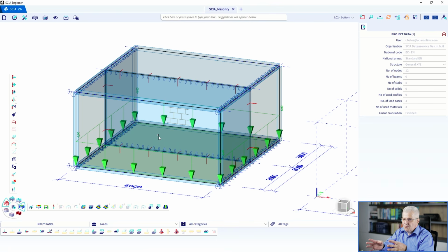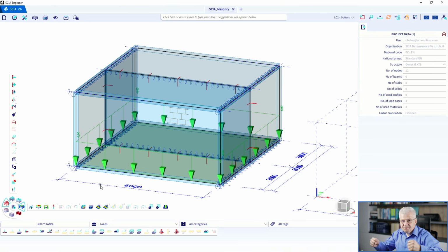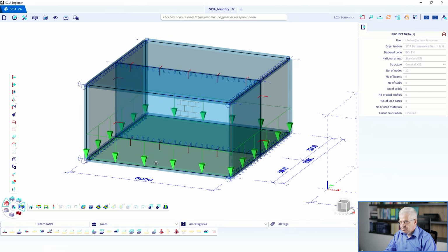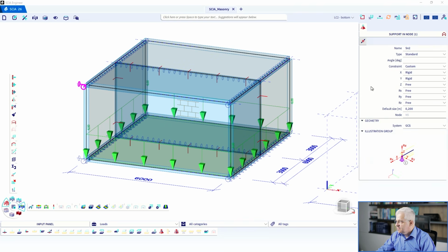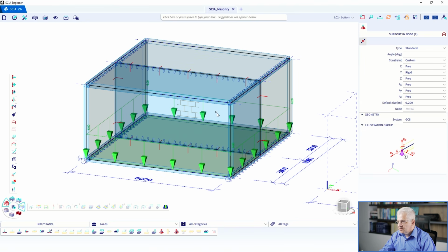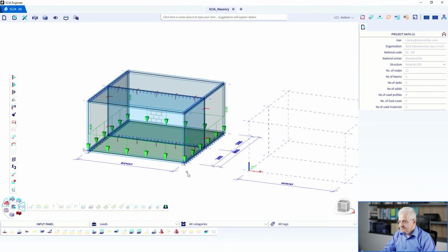I thought this is a very simple model. It's not the most realistic model, but it's simple. We have only supports in Y direction and only one in X direction, not to introduce some tension stresses in the slab. So it should be simple, and maybe I should also remove this X from the model to leave only Y, and generally I don't need both of these supports. This is enough if it's supported on the bottom side.